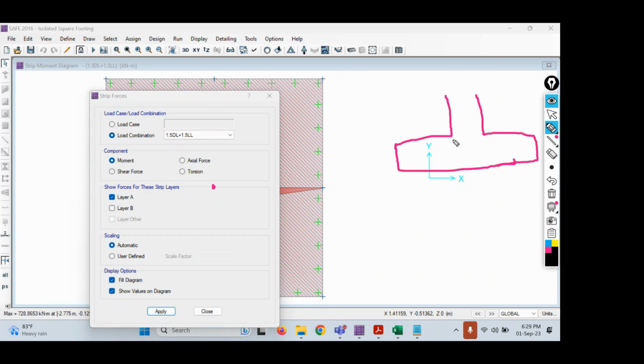Right. So at this particular portion, the cracks will get initiated at a 45-degree angle. Here the column will be stiff enough to resist the loads. So this portion will be very stiff to resist the loads. Why is it very stiff to resist the loads? Because the load will be coming from the column and the reaction forces will be at the bottom.